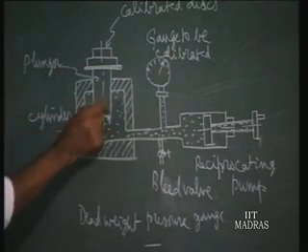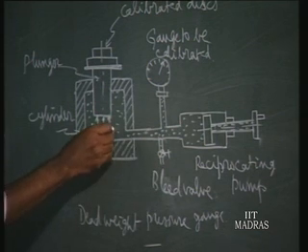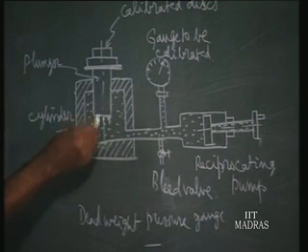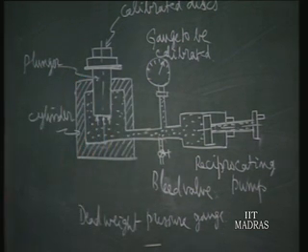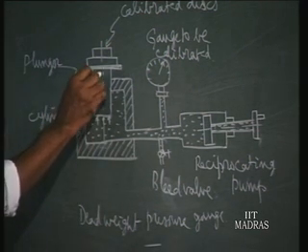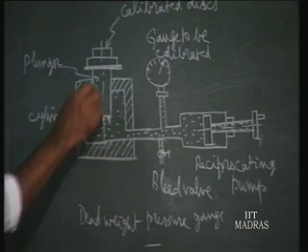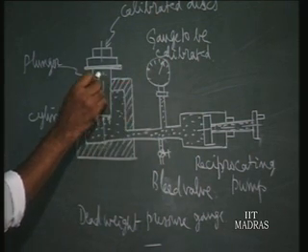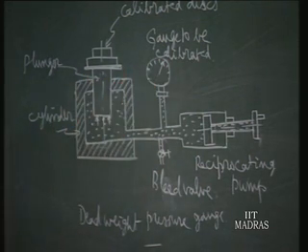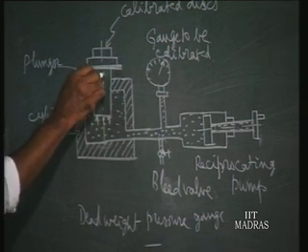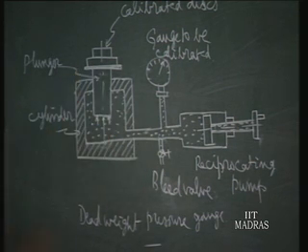So by rotating we can make this float: when the pressure developed in the liquid times the area of the plunger is equal to the weight of this plunger, then it starts floating. Some pressure value is written on the calibrated piston plunger, and whatever pressure is shown is the true pressure in the liquid, which can be noted down along with the pressure indicated by the instrument.